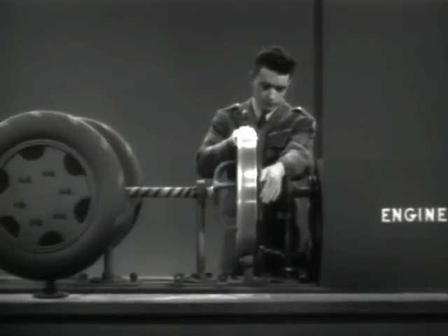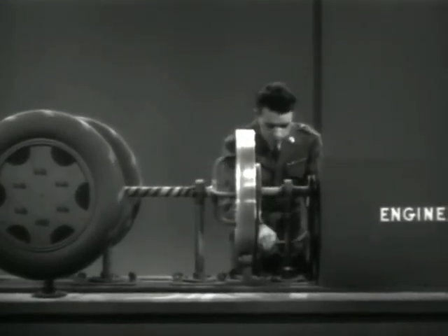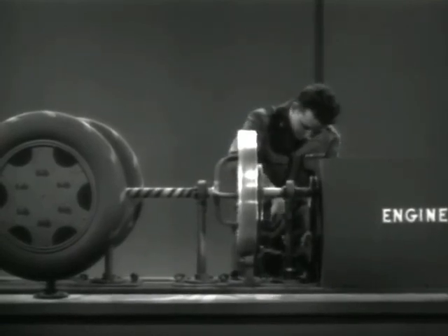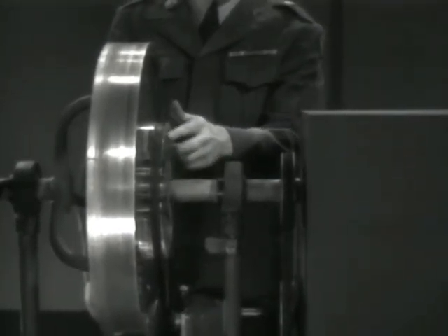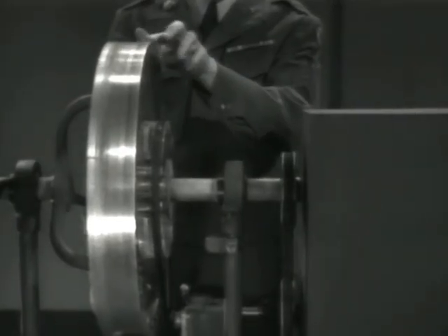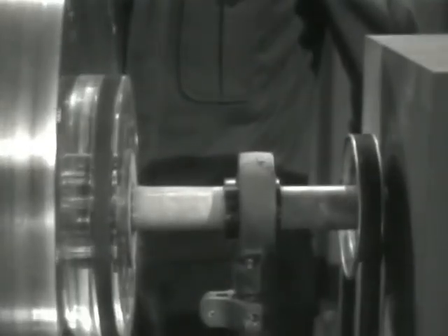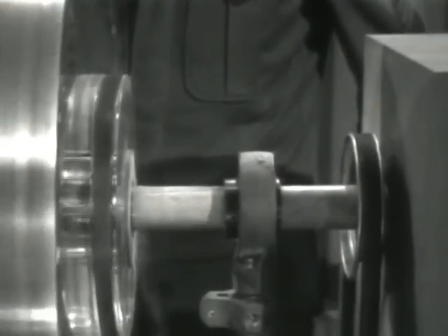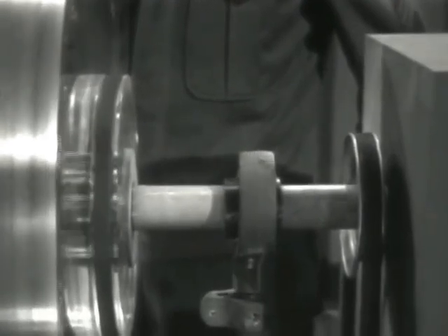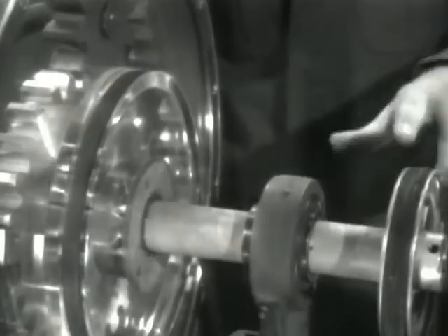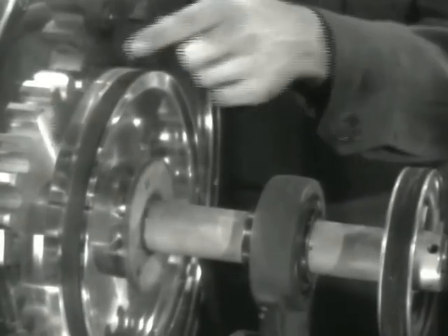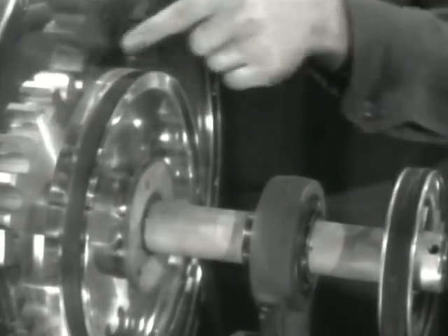We can get even greater variations in output ratios by adding another source of power to the planetary gear setup, giving us two inputs. One input is used to drive one of the gear members, the ring gear in this case. This input is run at a fixed speed. The other input is hooked up to the sun gear, and its speed can be varied.